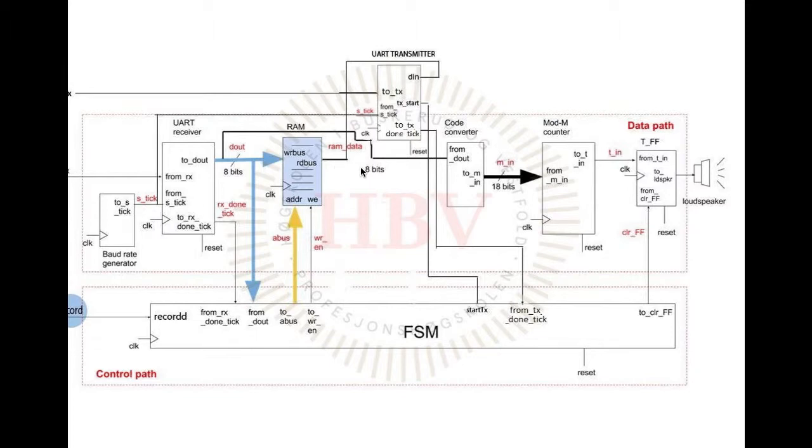When we set up this block diagram, we have to keep in mind what stage 3 required. We were to send data from the FPGA to the computer. That's why we need the UART transmitter. These components have a clock and a reset function. It also has an input from the baud rate generator, as you can see here.